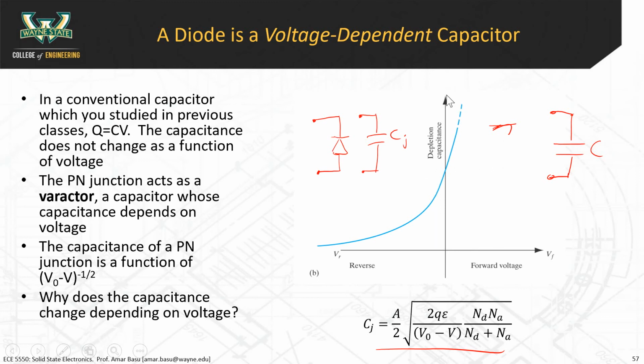Yeah, you can see it right here. This is the depletion capacitance on the y-axis. If you want to minimize the depletion capacitance, operate it in this region where it's lower. That's one of the reasons why, if you want your photodiode to work at high speed, you have it at the end of your fiber optic communication line, right?